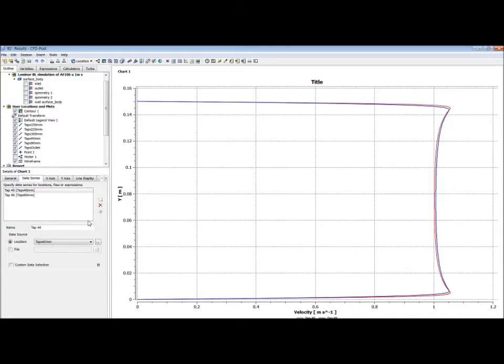So now you can see two different velocities, and you can keep on doing this for tap 150, location tap 150, apply, create a new one, tap 220, location 220, apply, then tap 300, location 300, apply, and then let's do one last one for the outlet, which is at 500 mil, and we'll do that tap of the outlet.